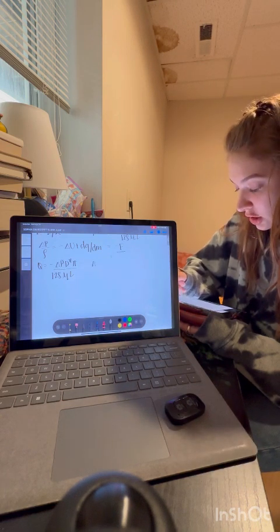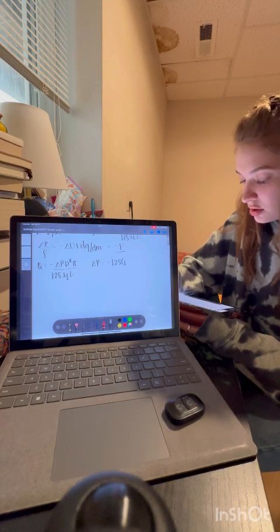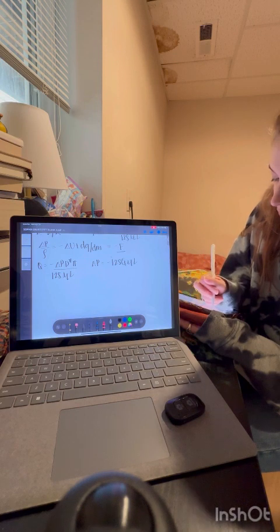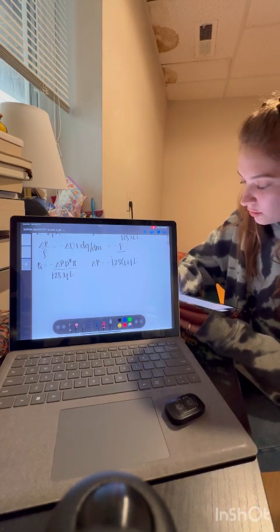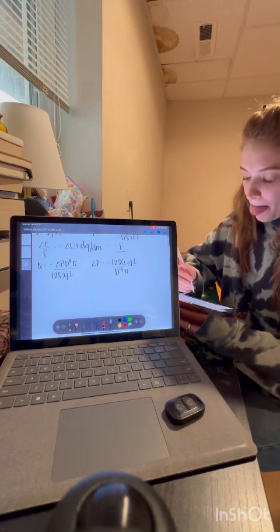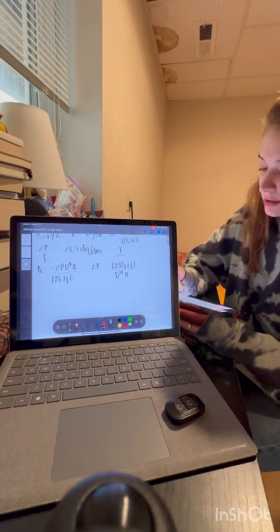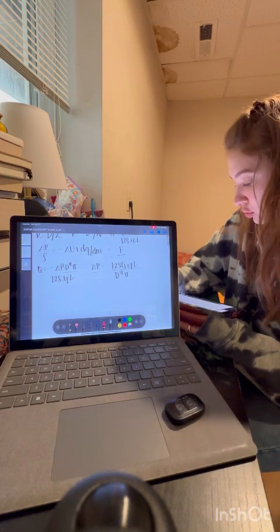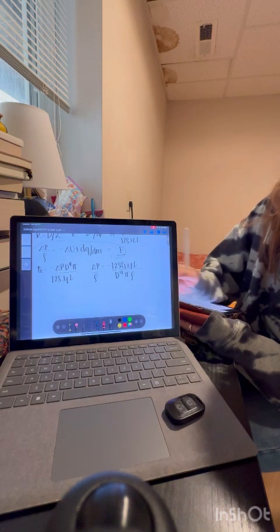That's going to look like change in pressure being equal to a negative 128 Q times our mu times our L, and then dividing the whole thing by a diameter to the fourth times pi. From here, the last step is to divide both sides by the density to be able to plug into our equation here.